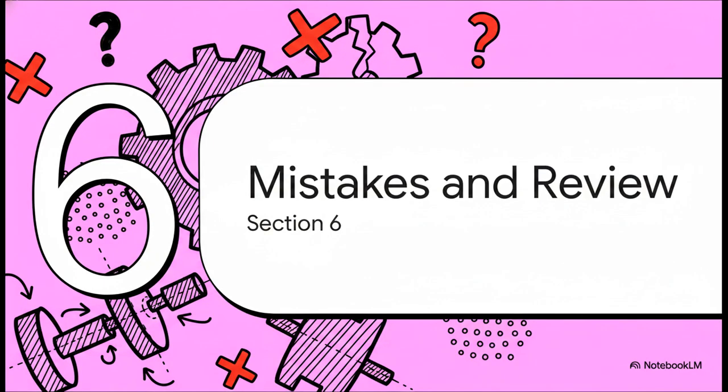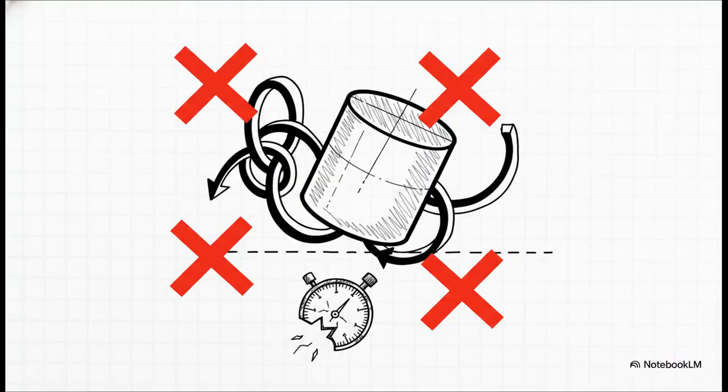All right, let's wrap things up with Section 6, Common Mistakes and Review. As highlighted by industry experts all the time, these are the frequent drafting and inspection mistakes you really need to avoid to prevent production delays and costly rework. First up, misidentifying datum features. If you pick a non-functional surface to base your rotation on, your runout measurement is entirely useless to the final assembly.